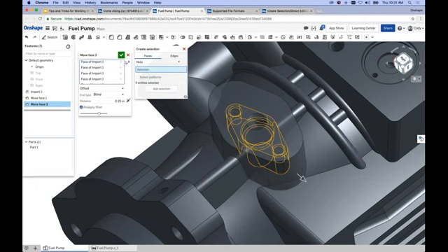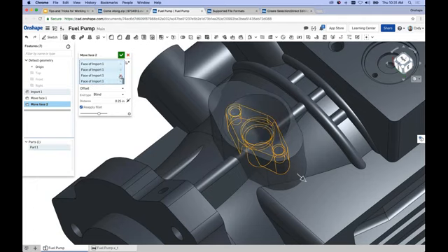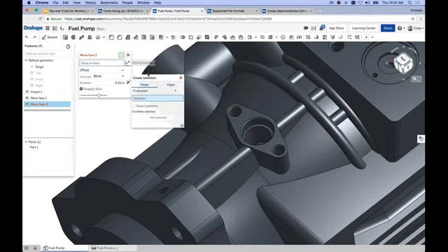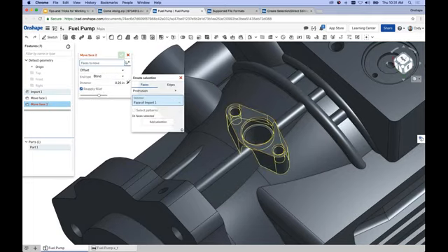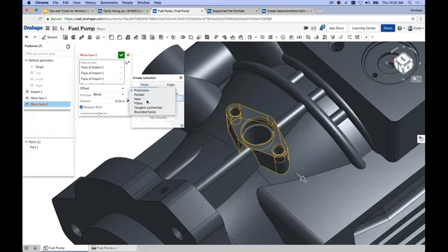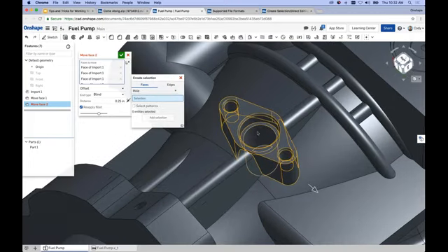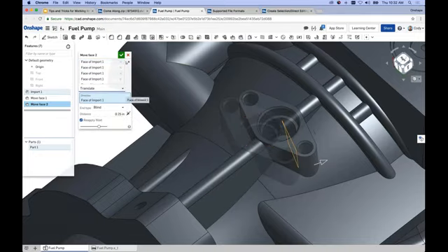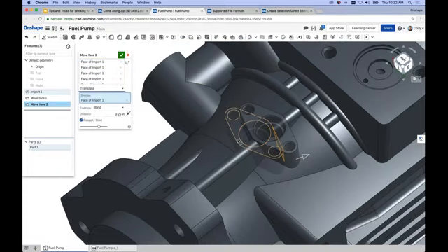So now, if we back out just a bit here, I can grab all of these. Try that one more time. Move face, create selection. Let's grab the protrusion and the hole. Okay. Make sure to hit add selection after you're done with one selection before you move to the next one. Right? Add. Now we don't want an offset. We want a translate. Now when you define a translate, it's important to define a direction to translate along.